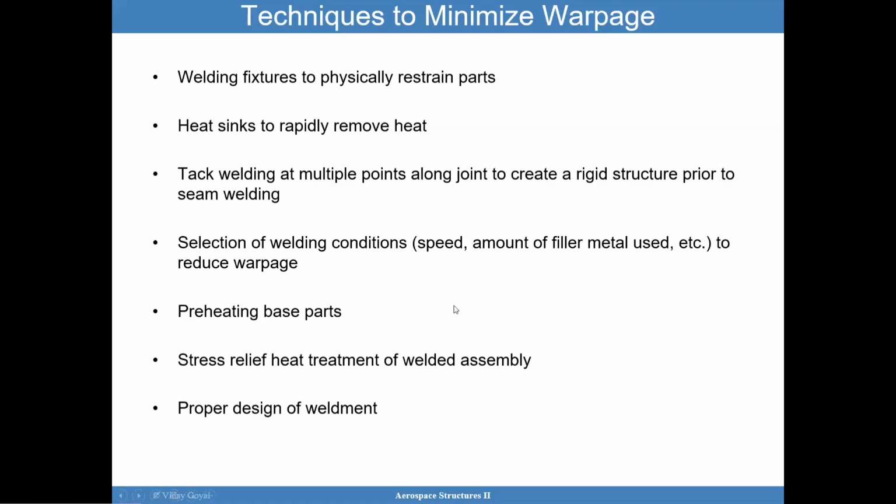So preheating reduces the stress concentration during the welding process, brings everything closer, when everything cools down together.